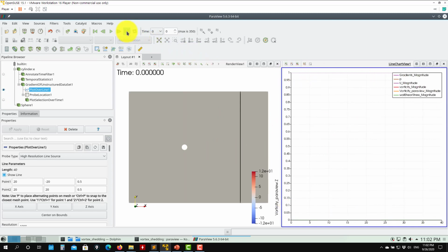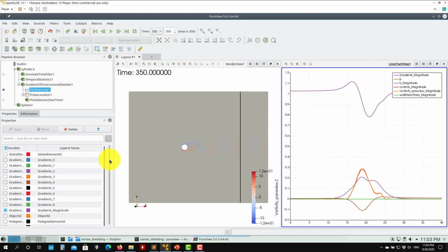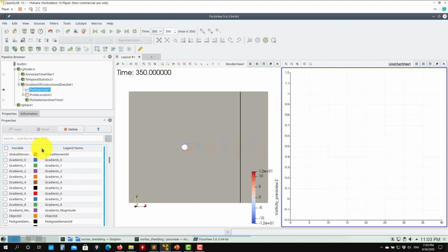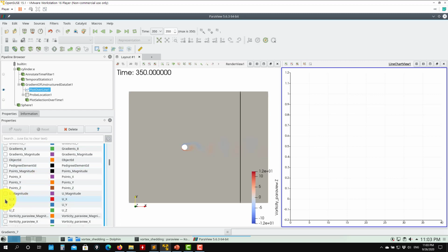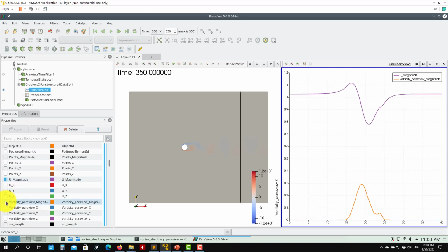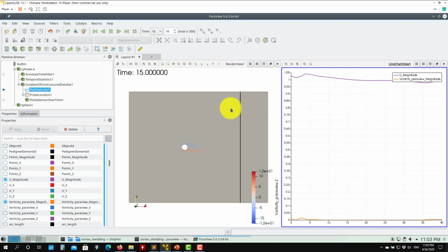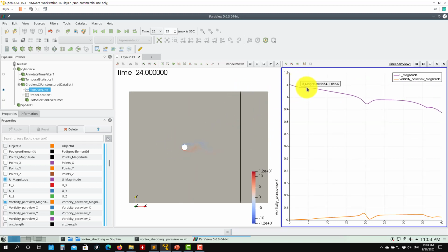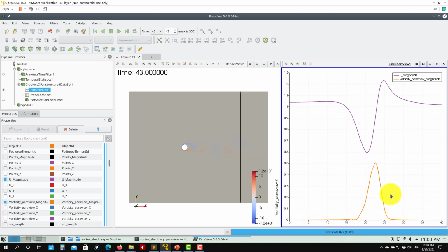You select this one that we want to visualize, and see that we can access, you click here, the valid view, and see that now you have all the fields. Selecting this one, you move here and you will have the options for what you want to see. Let's say that I want to see velocity magnitude, and probably also vorticity magnitude. Now you can press play, and it will start to measure that velocity here, and you can see the wake, where the wake is going.